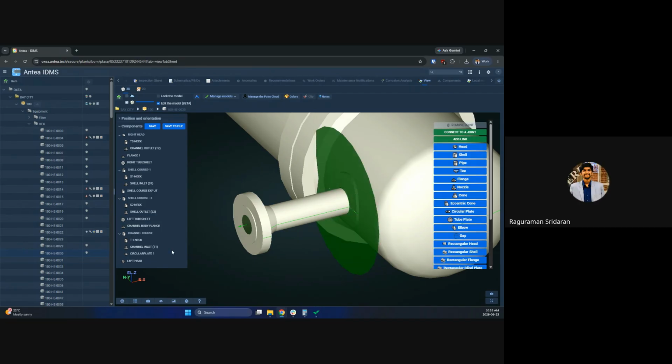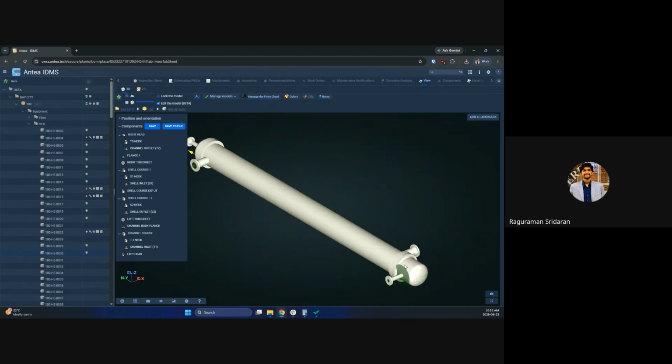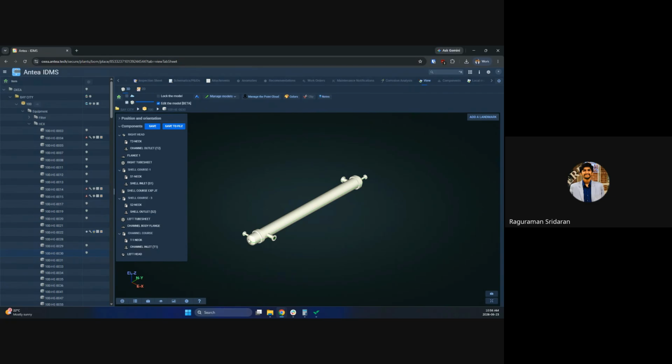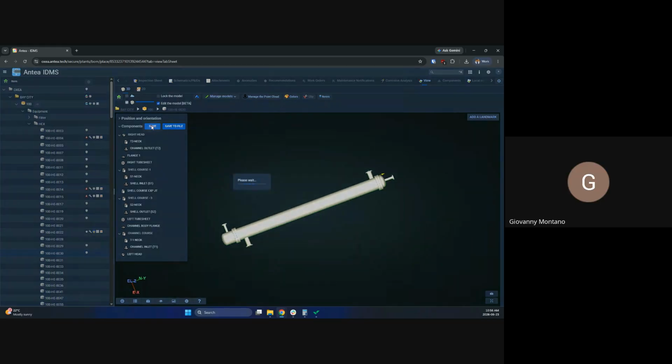Okay, good. But for this project, we are not creating the repads, so we're just creating only the nozzle necks and then the nozzles, not too much into too fine details. Pretty much whatever we see as outer components: shell courses, heads, body flanges, tube sheets, nozzle necks, nozzles, in some cases. Mostly those are the ones. But if there is something strange, please let me know. We can take a call from there. But repads, I'm not creating any repads so far for this project. Yes, okay, that's a good question.